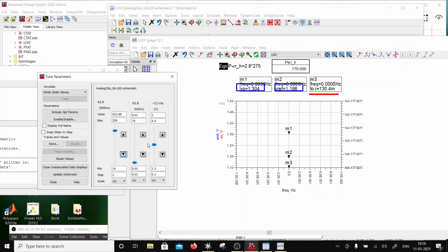And now I'm going to bump up the current. So right now the current is set by this. What is this gonna do? 1.3 volts. So it should be around 1 ampere current, right? If I go 1 ohm. Yeah. So is it holding? No. Okay, so I need finer graduation here. So right now this is 1 ohm. It's around 1 ampere current. This is 2 ohm. 2 ohm it's holding.